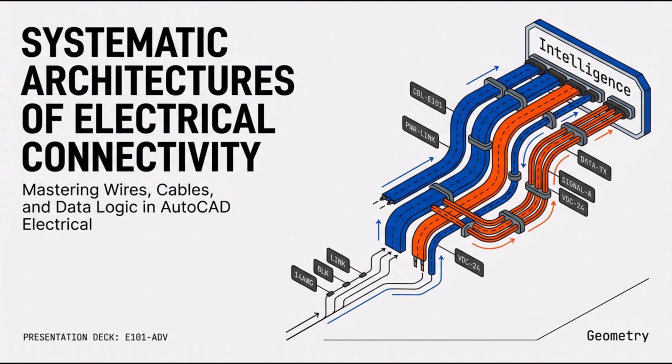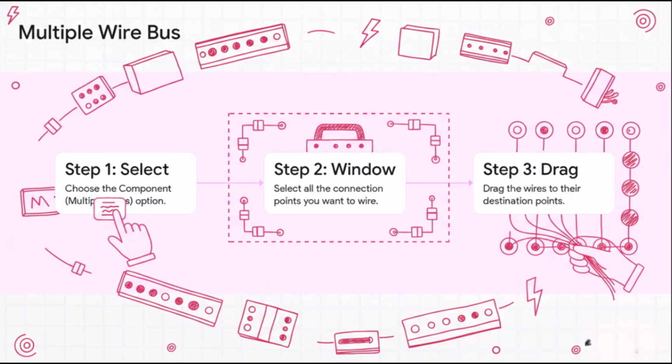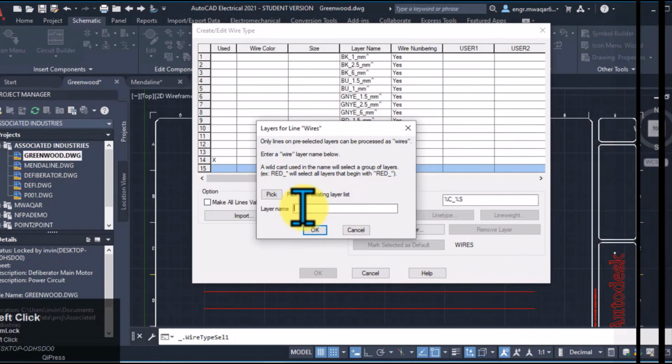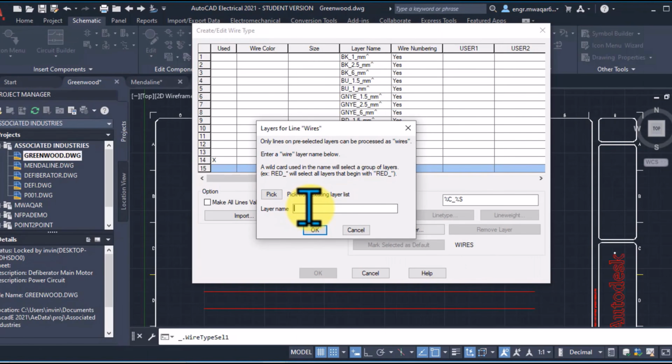Now, before we completely move off ladders, there is a variation mentioned in the source that I think really confuses people who are mostly used to basic house wiring or simple electronics, and that's the three-phase variation. Right, so everything we've discussed up to this point, the standard vertical ladder that is strictly for control circuits, the low voltage stuff, the brains of the operation. Nervous system. Right, but the heavy lifting, the actual high voltage power distribution to massive industrial motors, that is almost always three-phase power. And traditionally, three-phase buses are drawn horizontally, not vertically.